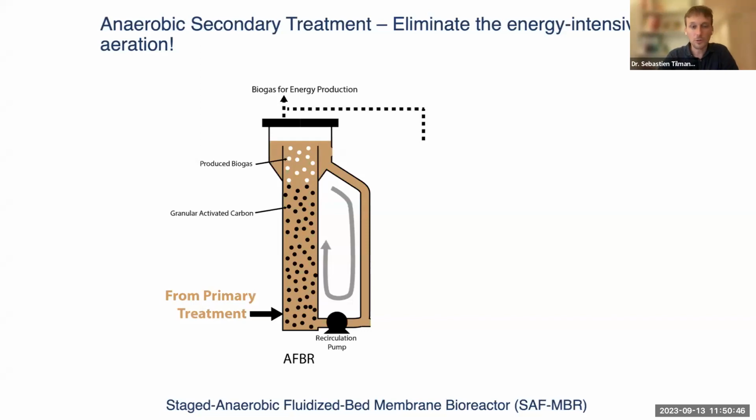Here, we're not using it to absorb chemicals the way that it's used in a Brita filter, but rather it's used as a biocarrier. So anaerobic organisms can attach to each one of these little grains of carbon and get retained inside the reactor. And they consume the organic matter that flows past them in the system.